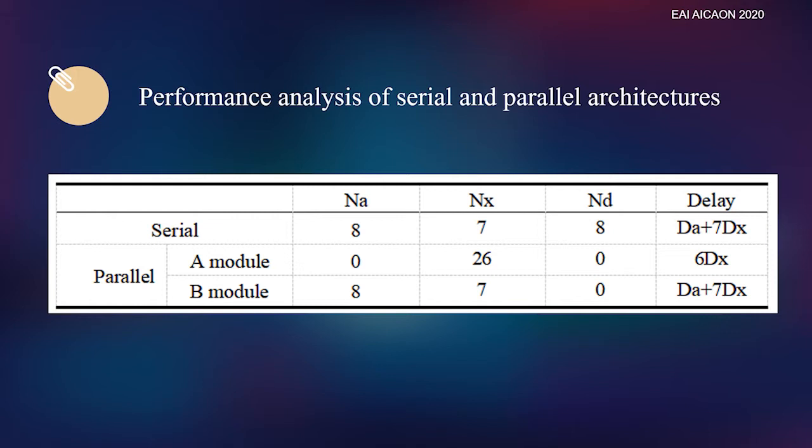In FPGA, XOR gates are scarce resources, with one XOR gate from each LE, and the overall resource consumption of parallel multipliers is relatively large. The multiplier of the serial multiplier needs to be saved for the next clock cycle, which increases the usage of 8 flip-flops. In FPGA, flip-flops are a rich resource and will not become a limiting factor.